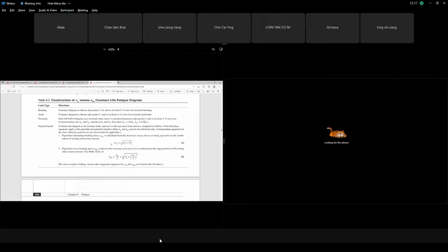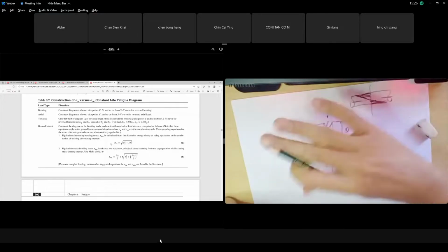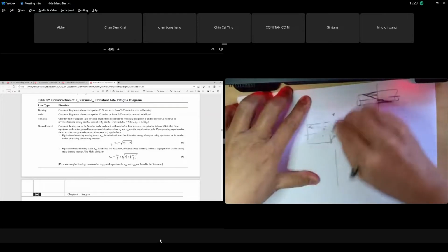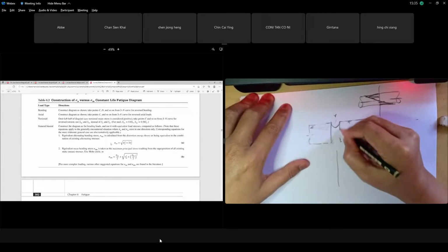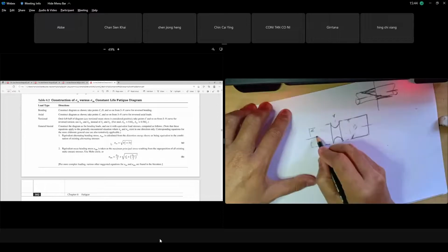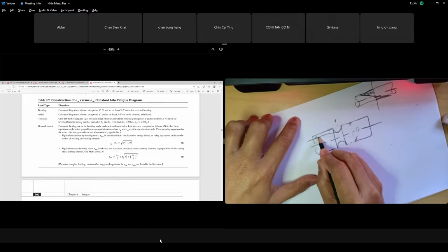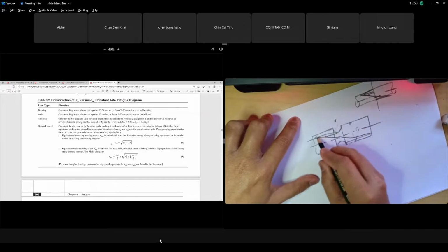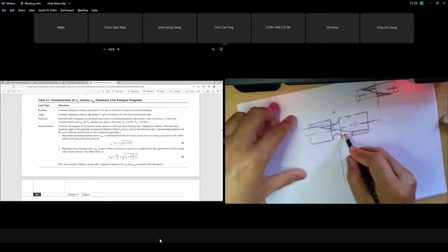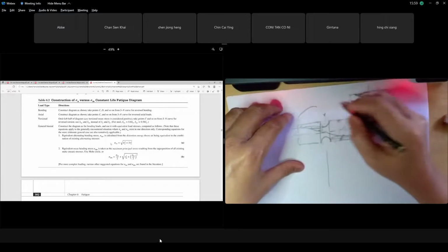But if you have a notch, because of that curve, that notch, your stress distribution is larger. At the neutral axis it is 0, and at the notch it becomes more distorted. It increases much more compared to without a notch, just a plain diameter. The stress distribution is much larger. Not just bending based on moment.